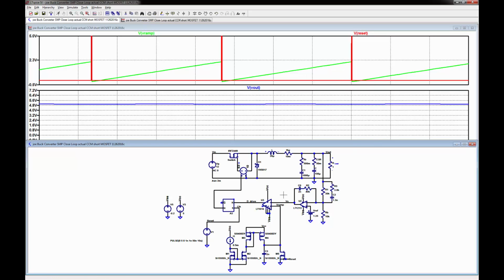And now we want to see V sub C here. V sub C comes up, and there's my duty cycle. It's the duty cycle is created here. Well, is that my duty cycle? Well, let's check, because this is the duty cycle coming out. There it is. It comes up because this is set. It goes high, and then it stays high until my ramp exceeds this V sub C. And there it is. Boom, it goes low. So there's my DT, and there's my offset D prime T.